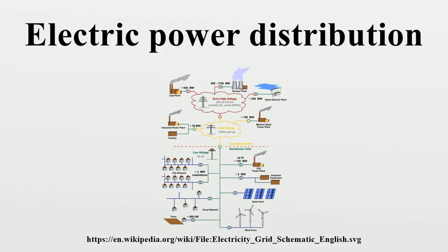Modern distribution systems. The modern distribution system begins as the primary circuit leaves the substation and ends as the secondary service enters the customer's meter socket by way of a service drop. Distribution circuits serve many customers. The voltage used is appropriate for the shorter distance and varies from 2,300 to about 35,000 volts depending on utility standard practice, distance, and load to be served.